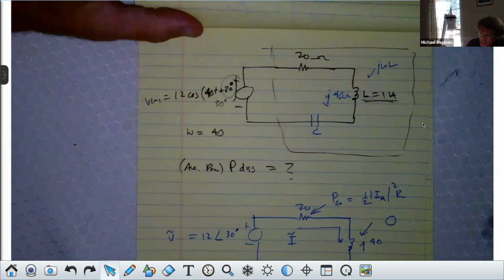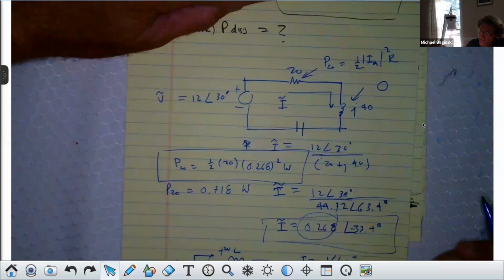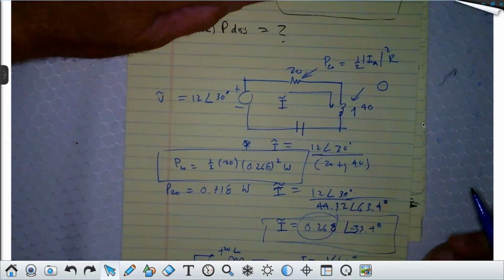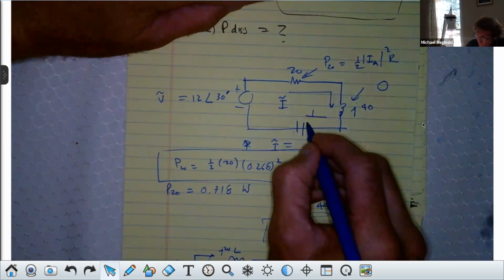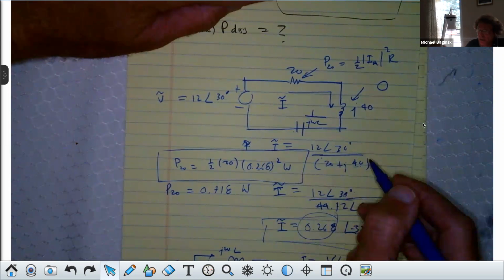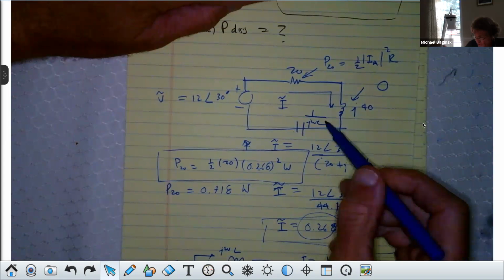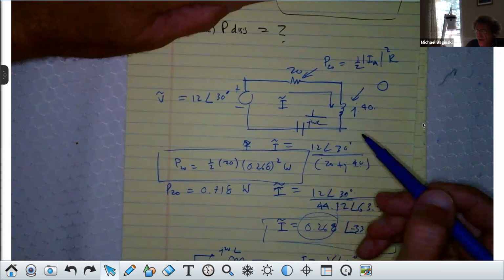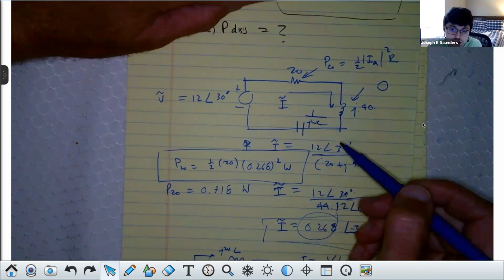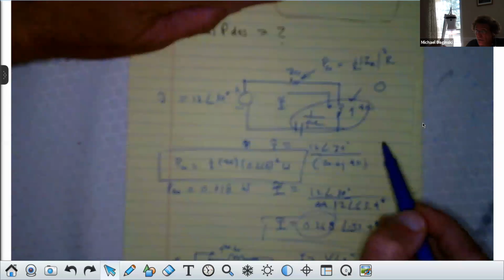Well, how would we deal with it? Down here, what would happen? If there's a capacitor, I'd have to put in an element that represents it, right? And that capacitor would have an impedance. The impedance of this capacitor would be 1 over J omega C, or simply minus J over omega C. Correct, class? And then when we figured out the current, we'd have to take J40 minus J over omega C. Correct, class? So you would have to adjust the reactive component. How many see that?